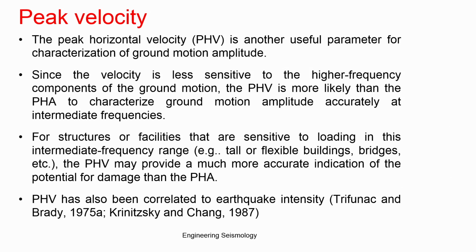The PHV has also been correlated to earthquake intensity by several researchers, where you can see how particular structures got damaged, and how much percentage got damaged with respect to PHV. So, whenever you have this kind of tall structure, flexible building, bridges and so on, acceleration is basically meaningless. You have to consider velocity data, the peak horizontal velocity, for the design.